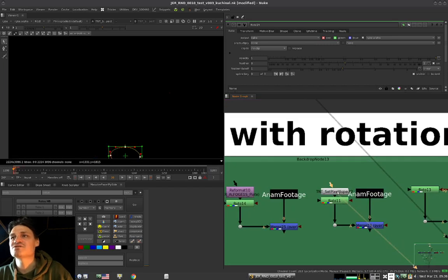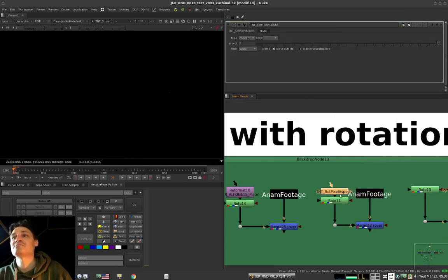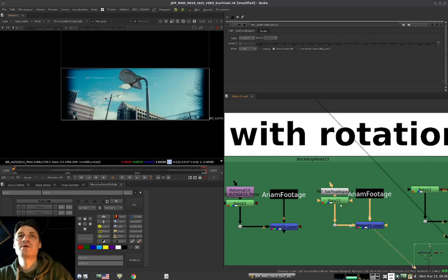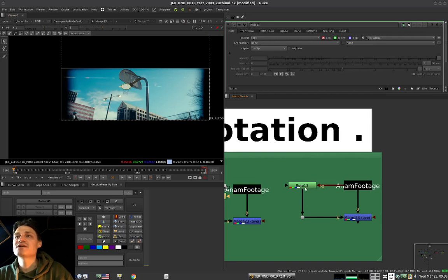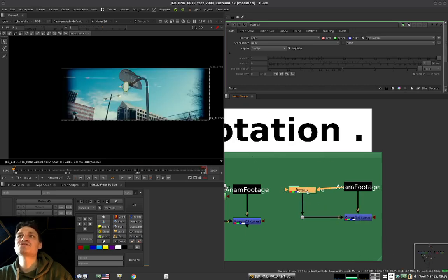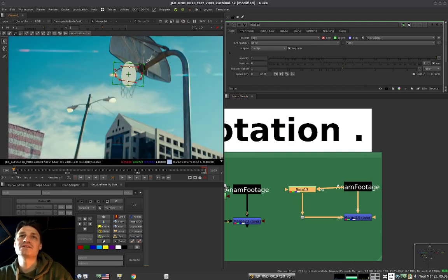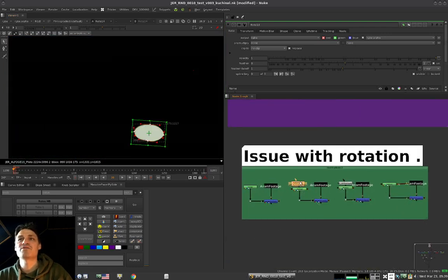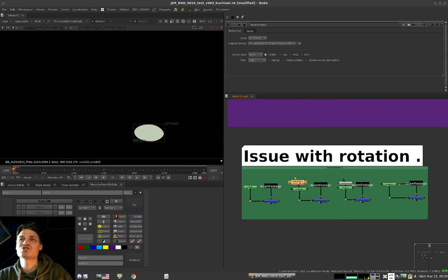Otherwise, you can use a trick just to set the pixel aspect ratio with the gizmo, aspect to 2. The bad thing here is you're losing your bounding box, but it does the job. Another thing you can do is pipe your Roto to the actual footage, set it to replace, and from now on it will do proper sync. Again, you will lose the bounding box here, so probably the winner will be the Reformat, where you just change the aspect ratio of the stream and keep going.